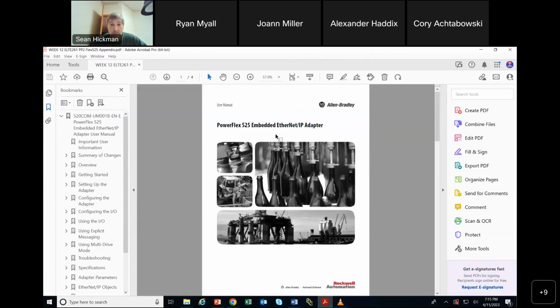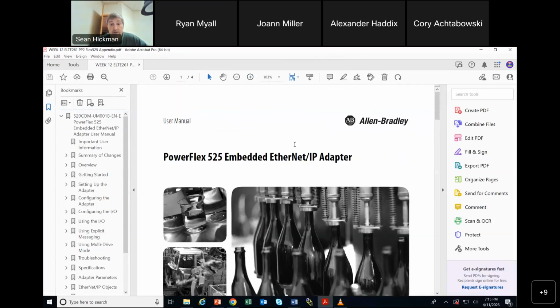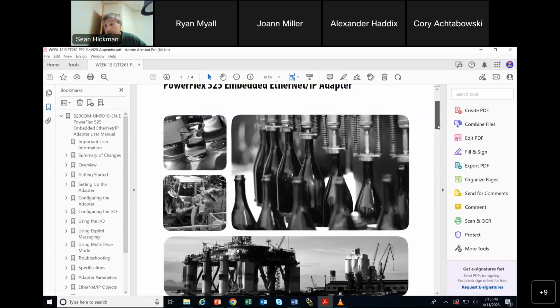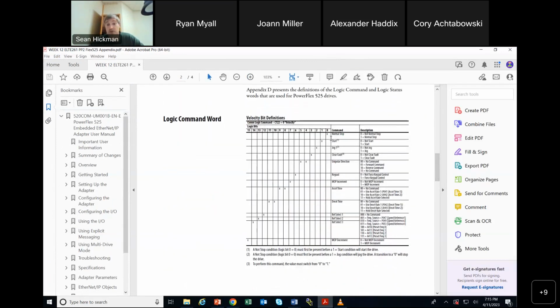So what we have is, you're going to set this up to be Ethernet IP driven. And so here is the control word that drives this. All right, here are the least significant bits. It's going to be 1110101101010111, whatever. If the least significant bit has a 1 here, it's going to be stop. If there's a 1 here, it's going to be start. So you think that your words are going to end with either a 0 1, or they're going to end with a 1 0.